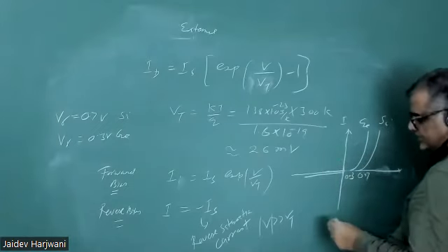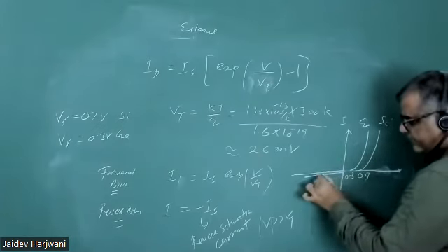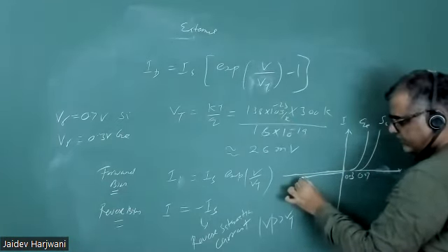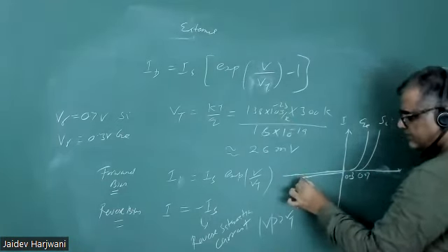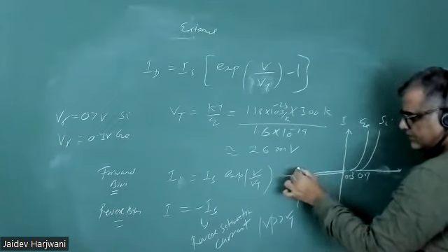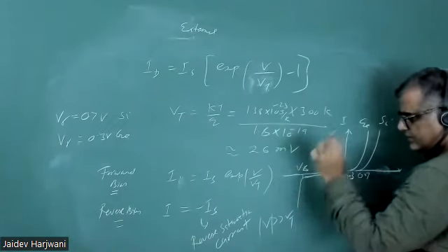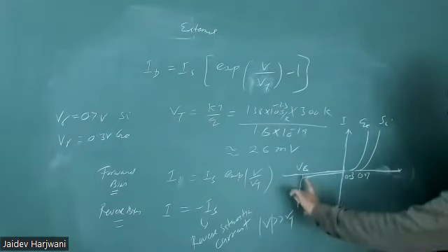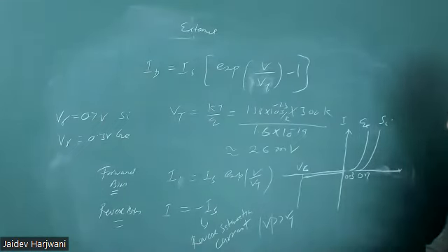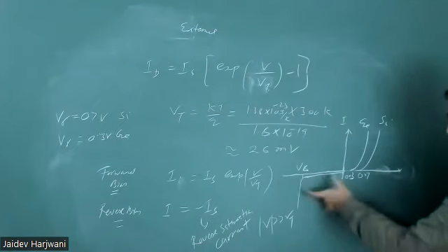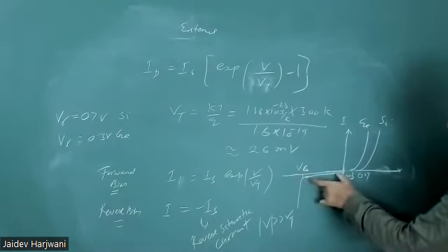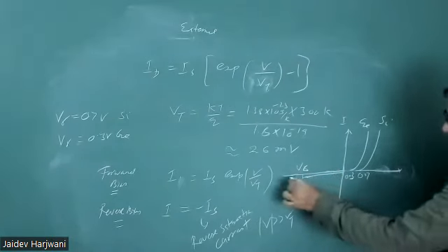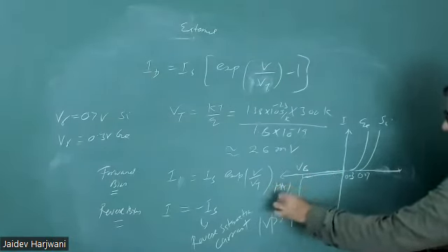Current is opposite. So this very negligible current will flow, and if you keep on increasing the voltage, at a particular voltage, what will happen? Breakdown will happen. So far we are not interested in this region. We are assuming that my voltage is very low compared to the breakdown voltage. So my diode will give only a constant current, and that current is in microampere.